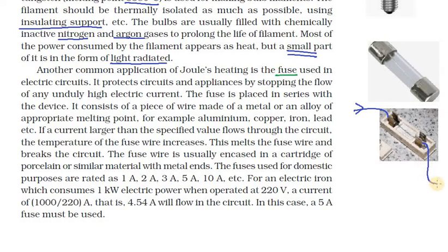The other part is connected to our household equipment, bulbs or a fan, whatever it may be. For example, a bulb needs 0.75 amperes to glow. If more current than that comes in, what will happen? The equipment will get damaged. Correct? So if 10 amps of current flowed, beyond 0.75 amps, the equipment would be damaged. That is why we make use of the fuse.